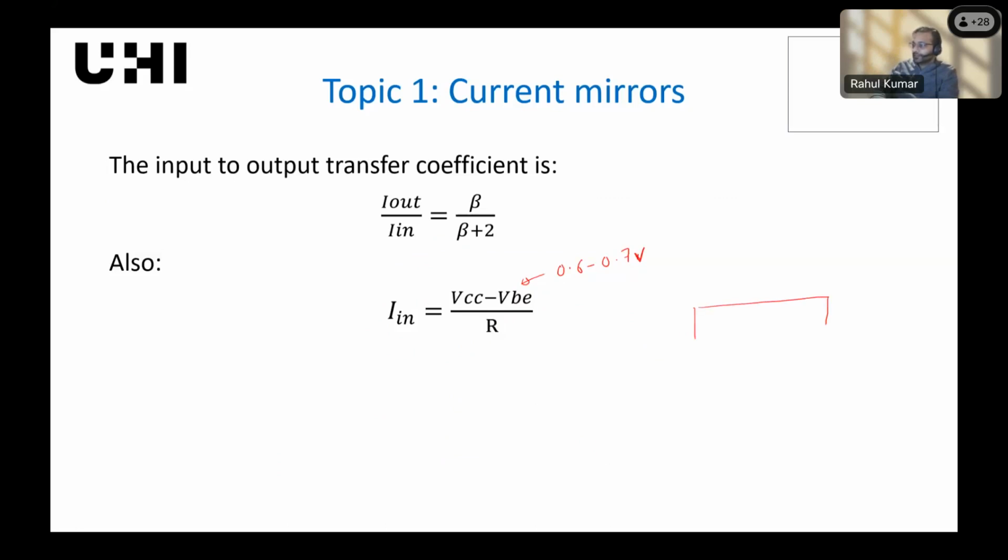Now, to explain it, your transistor is a 3-terminal device and you are connecting the base and the collector together, right? So all the current flowing into the collector will directly flow, there is no junction, right? You have this NPN transistor, so if you have connected them together, all the current will directly flow to the second junction.